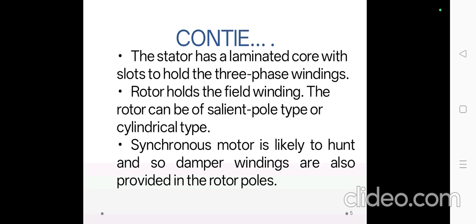Next, the stator. First of all, we have to see about the stator. The stator is a stationary armature. This consists of a core and slots to hold the armature winding, similar to the armature of the DC generator. The stator core uses a laminated construction. It is built up of special steel stampings insulated from each other with a varnish or paper.